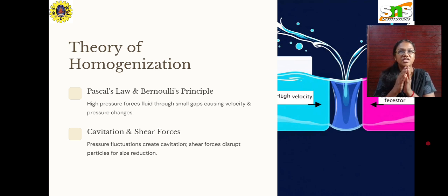And cavitation and shear stress: vapor-like bubbles form and collapse, generating intense energy among the particles. These implosions combine with very strong shear forces from a very high speed fluid flow, and they disrupt and break down particles for much more effective size reduction and dispersion.